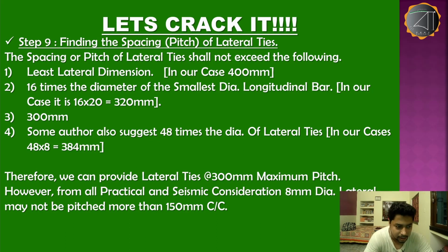Third point is 300 mm, and fourth one is, some authors also suggest 48 times the dia of lateral ties. In our case, 48 multiplied by 8, it is 384 mm. Therefore, we can provide lateral ties at 300 mm maximum pitch. However, from all practical and seismic consideration, 8 mm dia lateral ties may not be pitched more than 150 mm center to center.